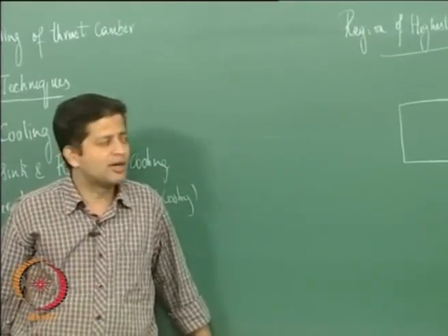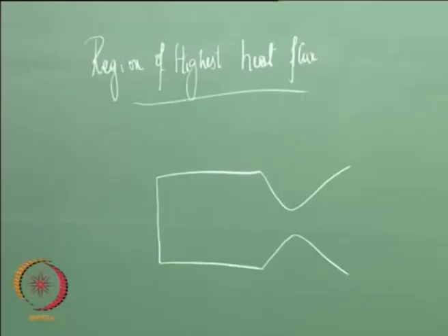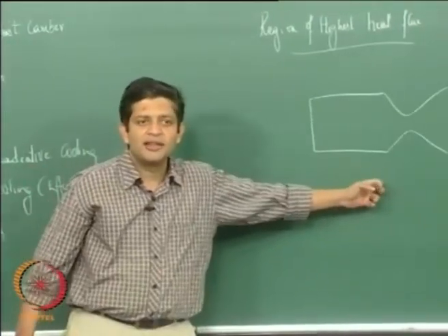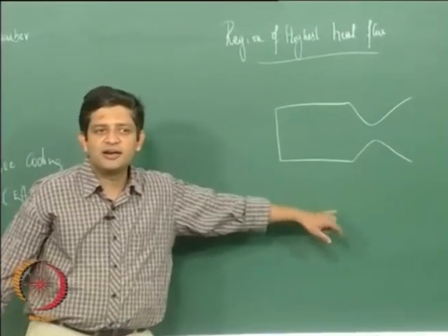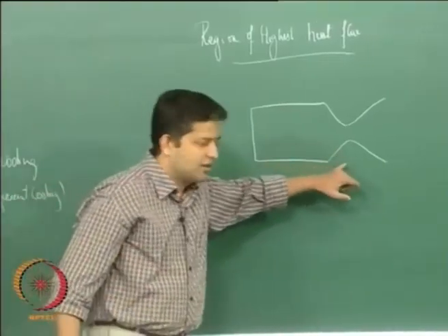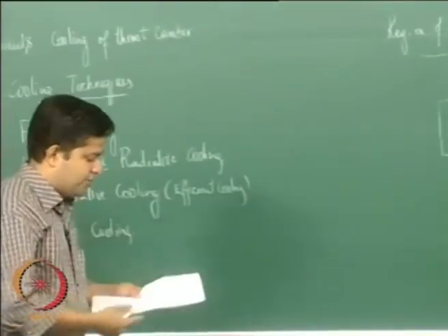If you look at this, where do you think the mass flux would be highest? It is at the throat, and that is where you will find that the heat transfer coefficient will be the highest. Okay, so let us try and derive that.